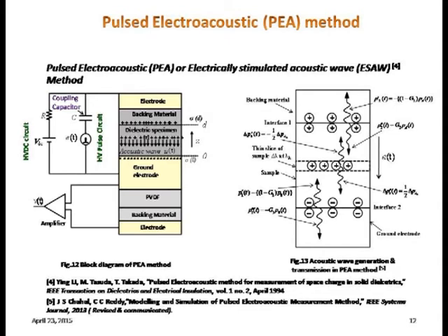So to avoid that problem, we need at least a certain thickness of this insulation, which I will come back to. Now here is the PVDF sensor, and below that some backing material is also used. In this case, this is also PVDF material, but some carbon particles are included to make it conductive and to avoid reflection at this interface.